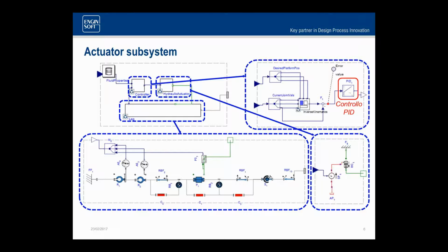The main problem of PID controller-based design is the tuning of the PID parameters, the PID gains, because small changes in these values can lead to very different system behaviors, and you need to have a procedure to tune these parameters as much as possible in order to have a system that behaves as you expect. This is the problem that we are going to analyze today.